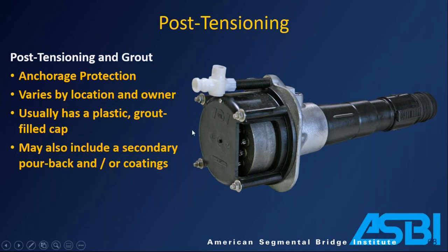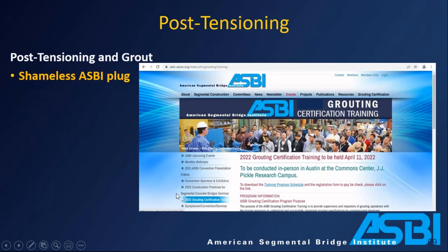Depending on the jurisdiction and sort of the corrosion environment, you may also be required to cover this in an epoxy or a mastic. You may be required to put a secondary concrete cap over it for protection. Again, read your specs carefully on those.